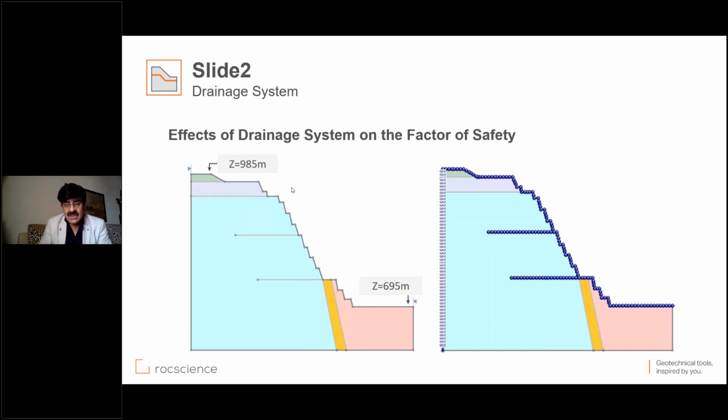The advantage is that, based on the site conditions and what you think is implementable, you can carry out schematic arrangements of the drains to be provided, and then try to simulate that arrangement through modeling like these, including the length and the angle, etc., of the drainage system that you plan to provide, and you can see the improvement in the factor of safety. So you can take a decision based on what works best for you.